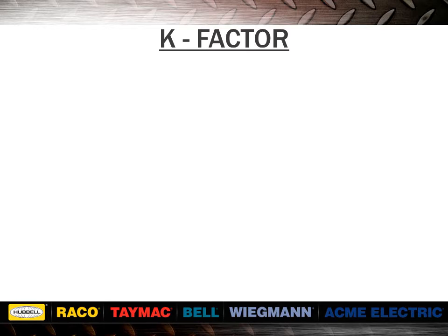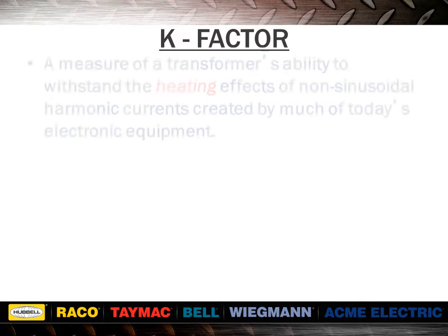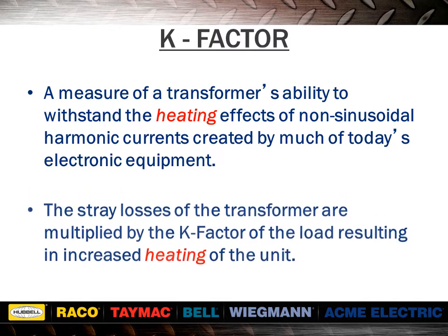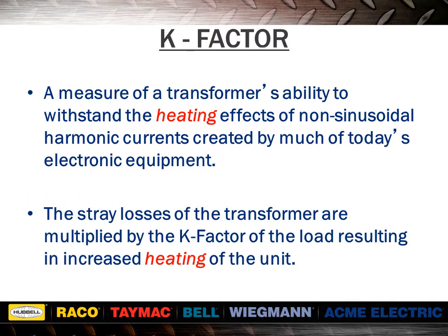The K-factor is a mathematical formula for calculating the heating effects of harmonics. It is a measure of a transformer's ability to withstand the heating effects of non-sinusoidal harmonic currents created by much of today's electronic equipment. The stray losses of the transformer are multiplied by the K-factor of the load, resulting in increased heating of the unit.